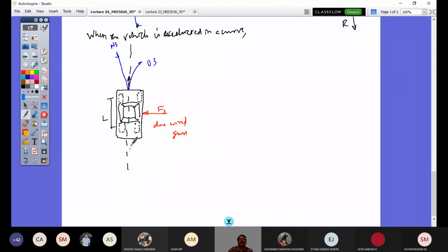If my vehicle goes straight and the vehicle speed is so high, maybe closer to the critical speed, and a side force acts, the oversteer effect would get into the force. If it is an understeer vehicle, it will go away from the force.